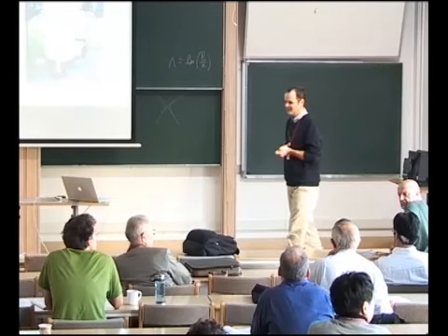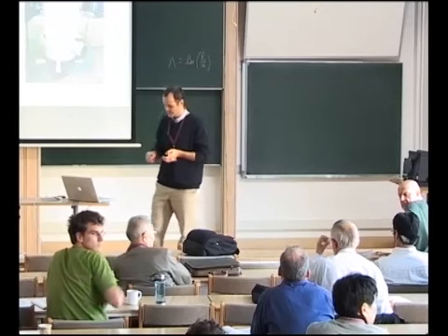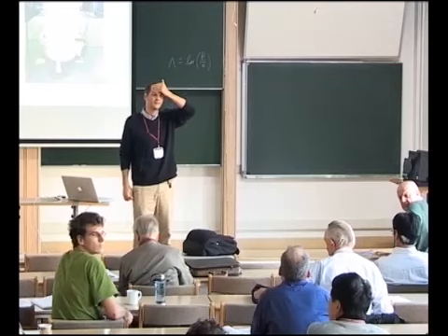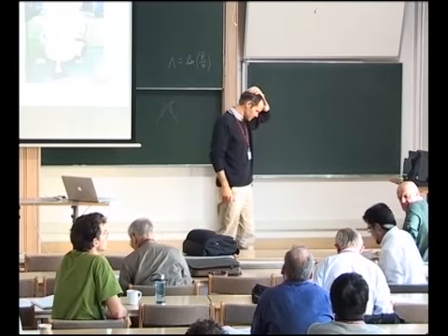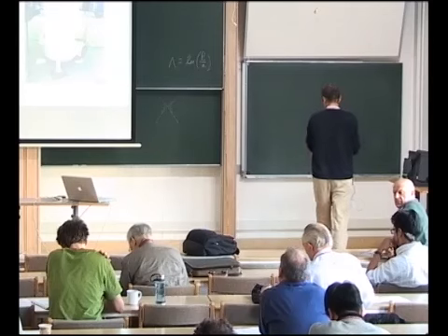Non-smooth field, you cannot differentiate it, only for small scale. Maybe you have an explanation for this, and maybe I need to think about this some more. But your assumption about being able to represent the vortex lines as passive scalars neglects two facts. One is that vorticity will stretch. It'll stretch in a superfluid just like it'll stretch in a classical fluid.